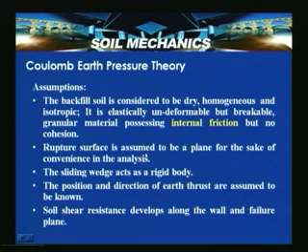So this has got some limitations which we will discuss subsequently. Rupture surface is assumed to be plane for the sake of convenience in the analysis. The sliding wedge acts as a rigid body. Once the failure occurs, it represents as if the portion of the soil got detached from the rest of the soil mass.